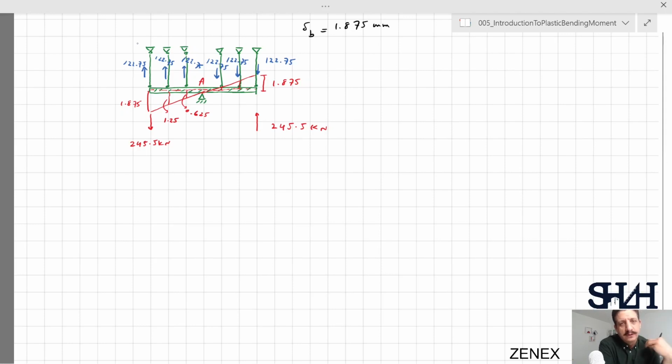So this load is called the maximum load, where all rods connected to this rigid element become plastic. This load is also called the plastic load. It means the load at which the whole system reaches a level where there is no capacity left. From this moment, the system is called a mechanism, meaning there is no capacity left for equilibrium and the whole system is now plastic to deform. In other words, if you increase the load, it moves and cannot be in static equilibrium.